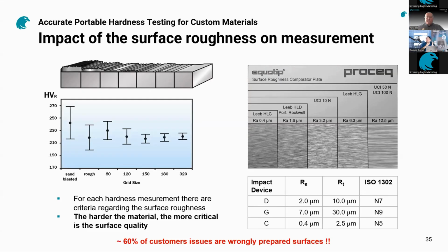And now, if we discuss, for example, 3% of 200, it would be plus-minus 6 Vickers. For the UCI, it would be slightly higher, so it's 4% on the laboratory scale, and by the user even 5%. So even 5% within that range is tolerable. Once more, it really depends on further details of that question. But we would be very happy if you have that question. Please forward it to us. We'll be very happy to answer that if possible.